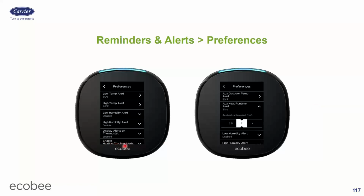Enable heating cooling alerts. Turn that on as well. This is a really cool feature where because the thermostat knows how long it takes to heat and cool your house at various outdoor air temperatures, remember we're trending that and collecting it into the cloud. Because it knows that, it also knows if something's not right. So if it's calling for heating and the space is not actually getting warmer or it's barely getting warmer, after a certain amount of hours, it's going to flag that and it's going to tell you.